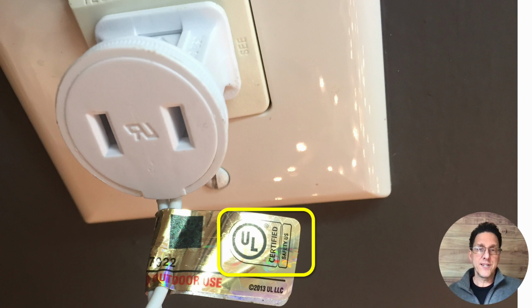So you might not see it immediately, but you may start to see products with this enhanced UL mark, and it might say UL certified versus UL listed, and that's fine, right? It's still listed, but UL is saying certified. So you may see some terminology changes in the code as well, because even now it says certified in 110.3(B), and so certified is basically the same thing as listed in this case.